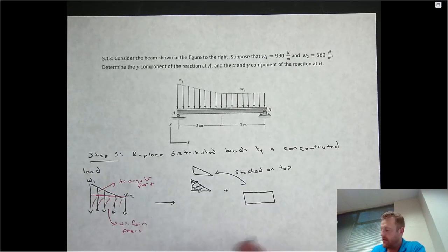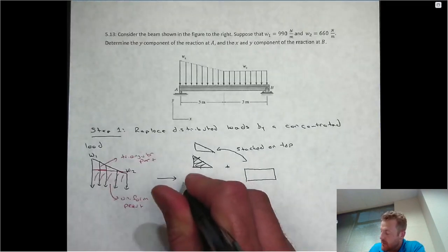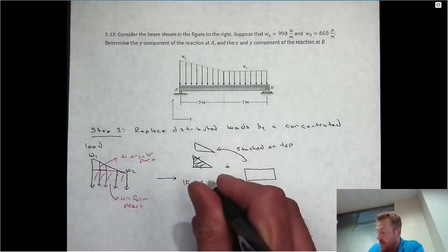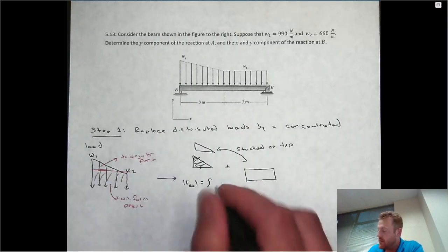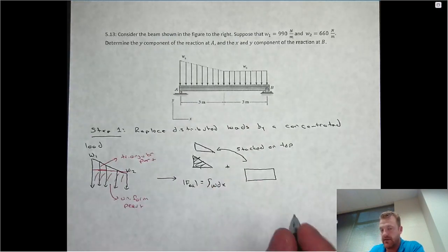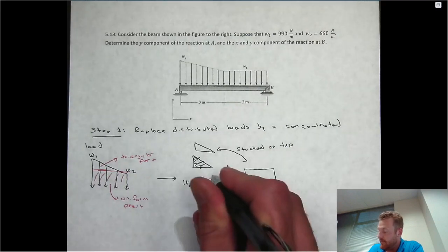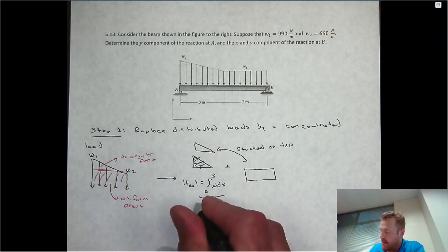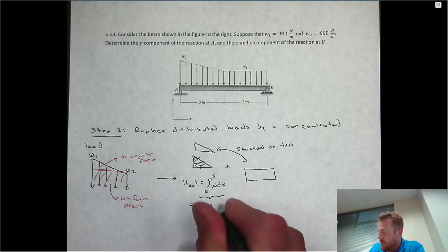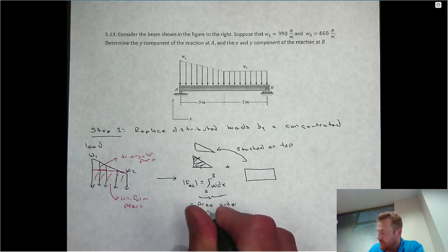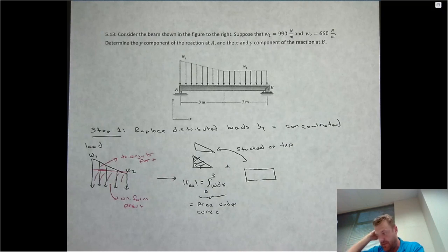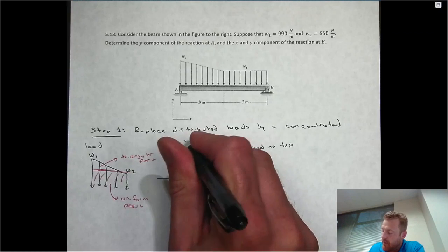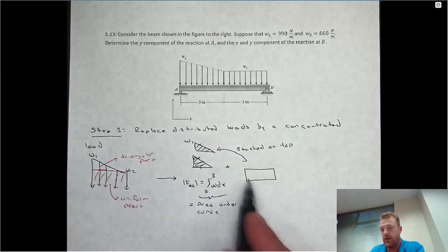The first thing that we need to do for both of these is determine the magnitude of the equivalent force. Remember that the magnitude of the equivalent force is equal to nothing more than the definite integral of that distribution over the area which it's applied. In this case, it would be from 0 to 3. However, up to this point in the text, rather than actually compute the integrals, we're just going to find the area under the curve of both of these distributions. Now be careful with this, because when you think about how tall the triangular part is, yes, it has an actual peak value of W1, but for the triangular part, we're accounting for the W2 part in the uniform part.